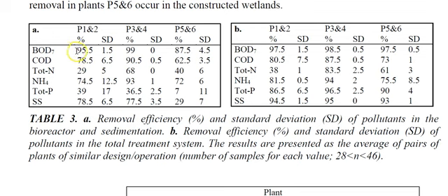If we look at BOD, for instance, most of it is removed in the first stages, especially in case 3 and 4. And we grouped plants 1 and 2 because they had very similar conditions, 3 and 4, and 5 and 6. So for BOD removal, there isn't that much gain by adding the wetland. While we see the case with the lowest treatment in the reactors reached almost the same total removal once we added the wetland.